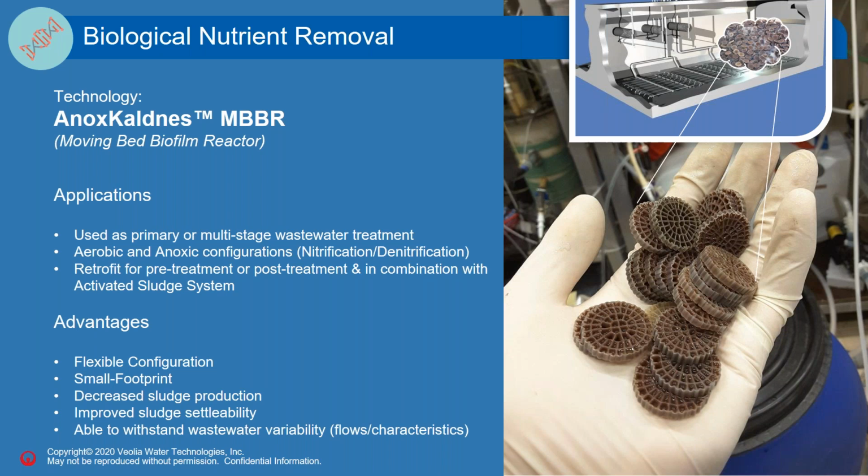We really like the MBBR technology for its diverse set of applications, but the basic idea with MBBR is that we have fixed film suspended carriers that we put into an aerated system, not dissimilar to activated sludge, but instead of keeping all of the solids in suspension, we're providing specific surface area for biofilm to grow on the fixed film media, and that provides a lot of advantages.